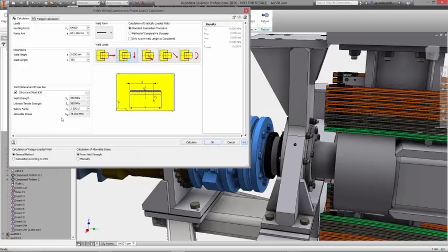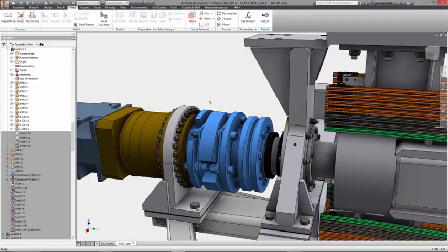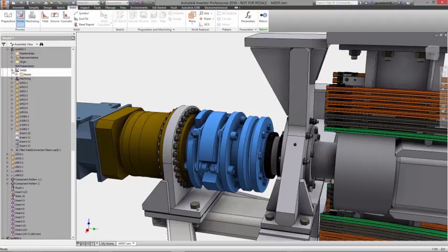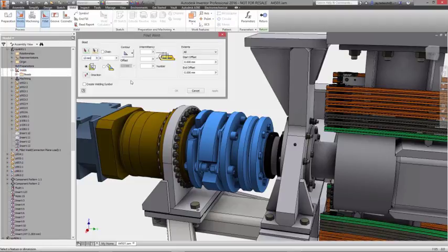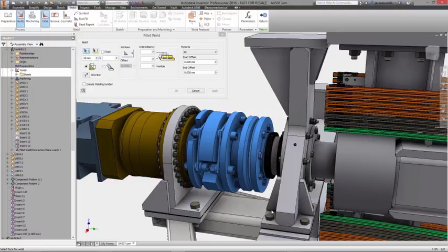And Inventor even goes a step further, with component generators that automatically create parts and geometry as you calculate what is needed in your design. Built-in calculators help you check the design of common joints, such as welds, solder joints, clamps, and press fits, to ensure your design will perform at the loading conditions your product will see in use.